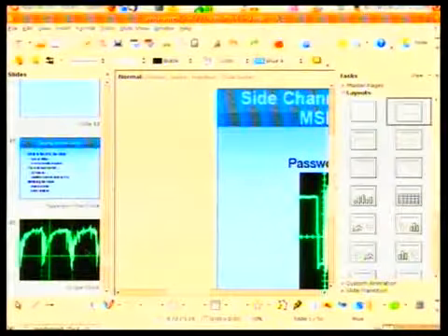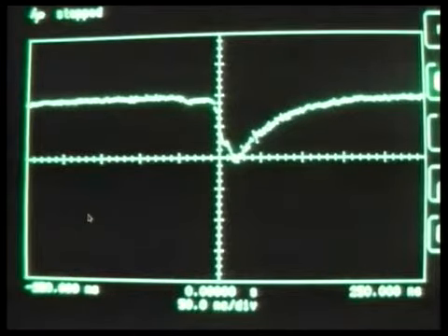How long did you say the timing glitch on the voltage rail had to be? I've had luck with about 45 nanoseconds. Oh, and you managed to generate that with the muxes and an MSP430. What speed's the MSP430 running at? If I jump back to the picture, no, that's not it. I'm not sure how much of this is affected by the capacitance of my probe, but you'll see that it's not a very square drop. So I was wondering if you could do it just with a cap from an I/O pin on the MSP430 going into the rail, just have a falling edge on the other side of the cap. You can. In this case, I used the muxes so that I could switch to a particular voltage. So I can add a capacitor to a test point on my board, get the capacitor at the value that I want to glitch with, and then flip everything over.